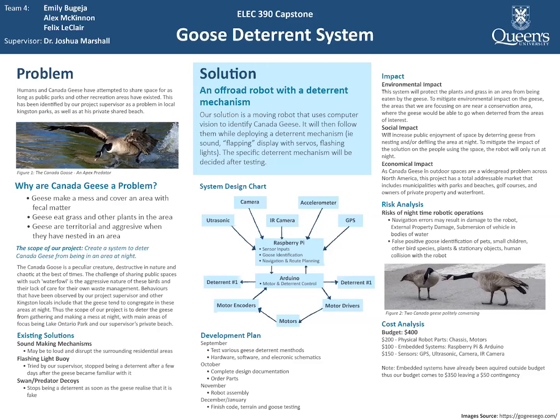So our next question is for Alex. How will you consider the variety of terrain your robot will traverse over? How do you ensure the robot's mobility? The robot will primarily be operating on safe, flat terrain as defined by geofences, and it will limit its movements if it detects itself leaning over too much on an incline as measured by the onboard accelerometer. Additionally, to ensure the robot can determine its speed and acceleration for proper traction, the robot is outfitted with an ultrasonic sensor to help determine the terrain beneath it that it is driving across.